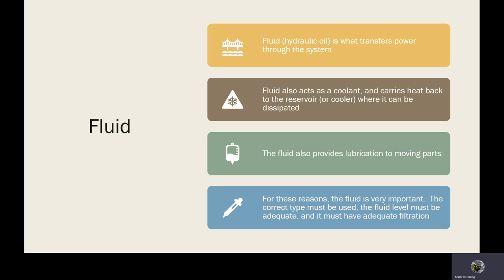So the fluid is the blood of a hydraulic system. It does many things, just like the blood in your body. It acts as a coolant, carries heat back to the reservoir or cooler where it can be dissipated. It provides the medium to transfer power. It lubricates. It's extremely important. Its viscosity must be as specified in order for it to work correctly.